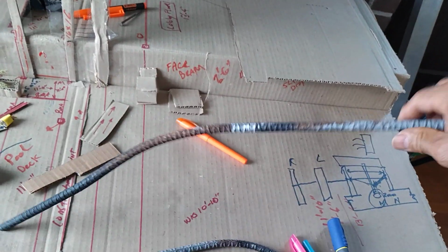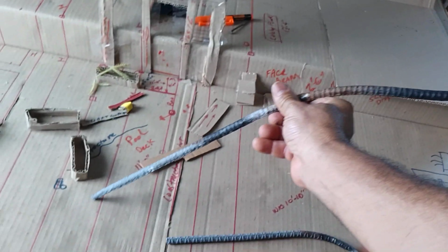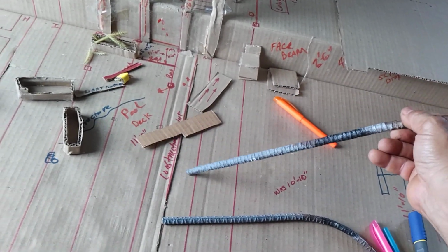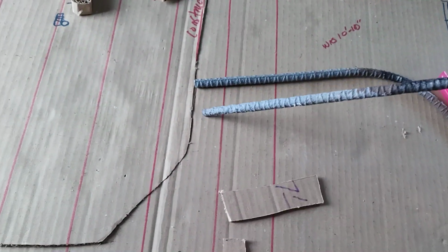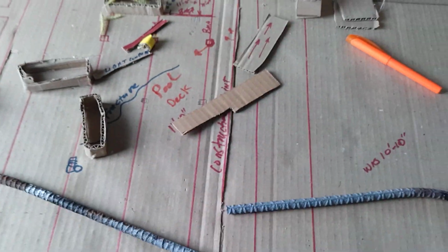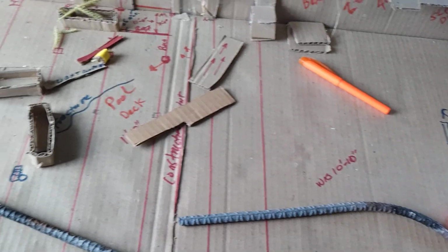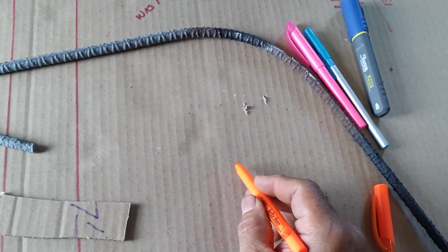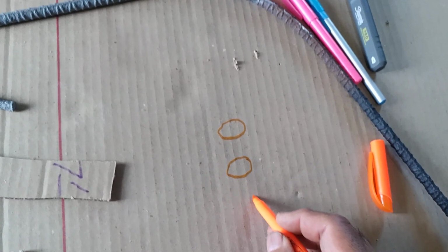It presents more like that, slope down on the underside. You see it connected to the underside of this deck into here. Down here we barely see it at all, but it's there. It's on the very underside, the very bottom of it. But it was supposed to be three sections, as I showed you in the previous video. It's supposed to have been configured with three pieces of rebar. So the joint, 1, 2, 3.